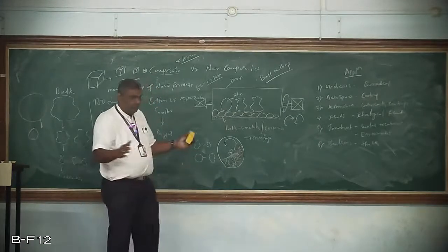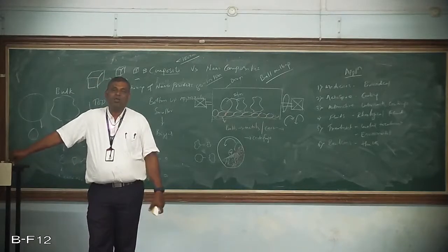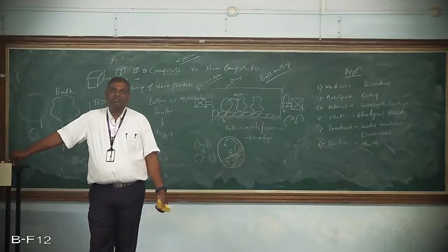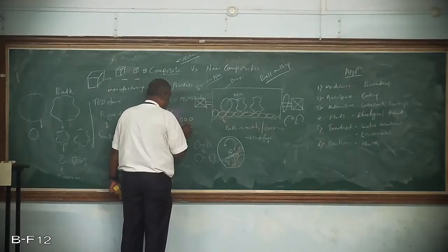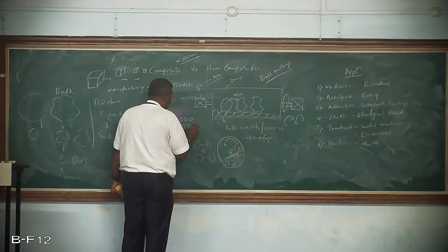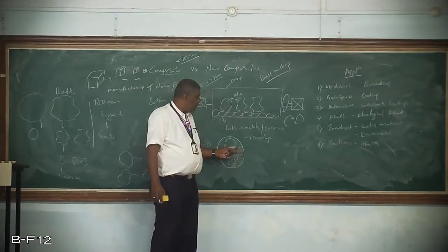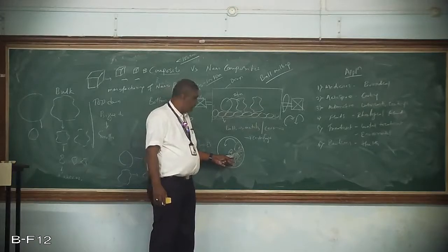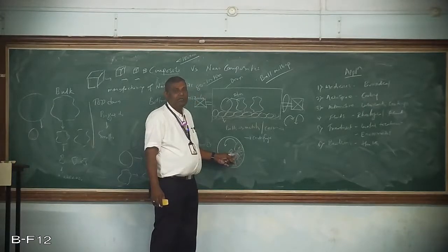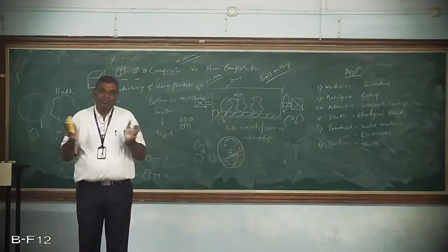Suppose I have around 10 grams or 20 grams or 1 kg of powder particles, all the sizes are not the same, the shapes are not the same. So we get variation of the shapes. We can't have all uniform sizes. There will be a lot of variation because we don't have any control over the falling of the balls from top to down. Okay, so this is the disadvantage of this ball milling process. But this is the basic process to convert bigger size material to smaller size.